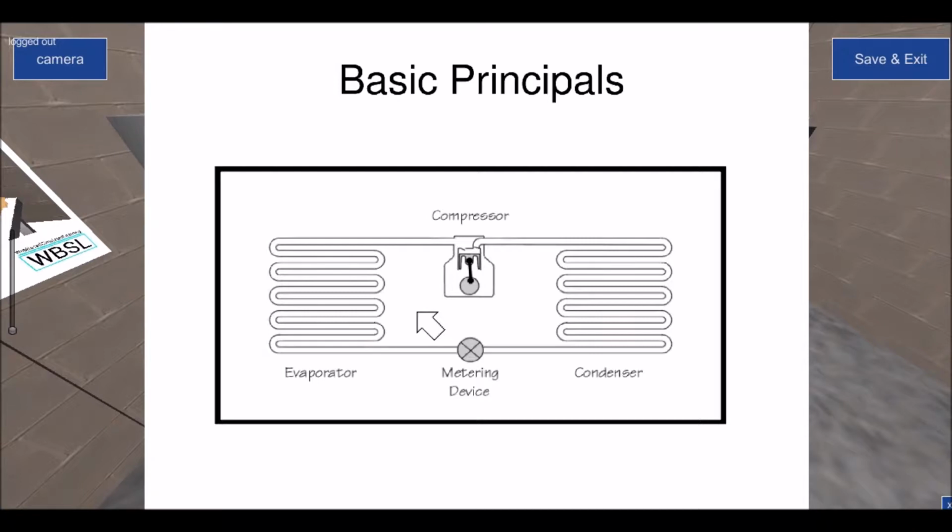On the other hand, with an electronic expansion valve, because we can get instantaneous reaction, we can minimize the superheat value. We can lower that superheat value because we can instantaneously shut down the solenoid, the electronic expansion device. We can shut it down within a split second, therefore allowing the liquid to boil off before it gets back to the actual compressor itself.